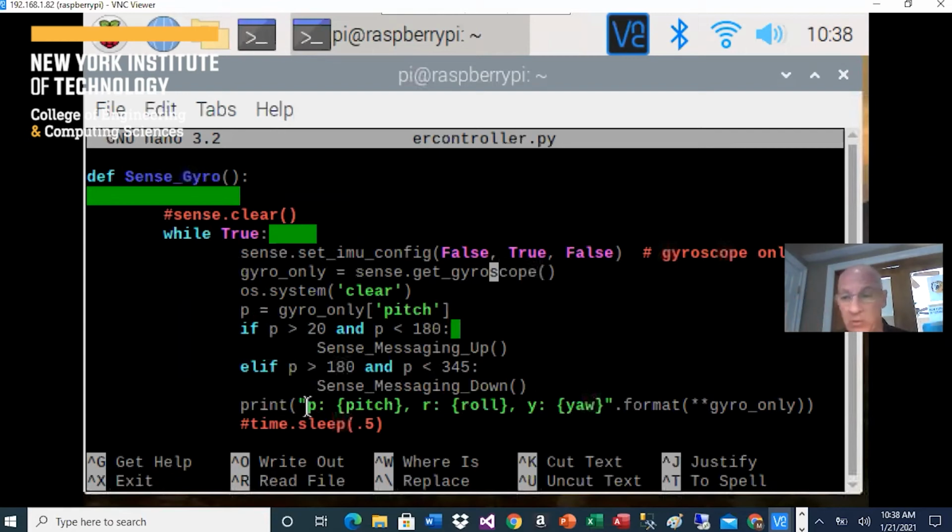And this is where the research piece comes in. Who knew, right? We chose to use the accelerometer because the data that came from the gyro was unreliable as far as what we wanted to do. And when you're dealing with a 150-pound robot with high torque motors on it, you don't want it running over somebody or causing damage. We didn't want something unpredictable. So we chose, as developers,